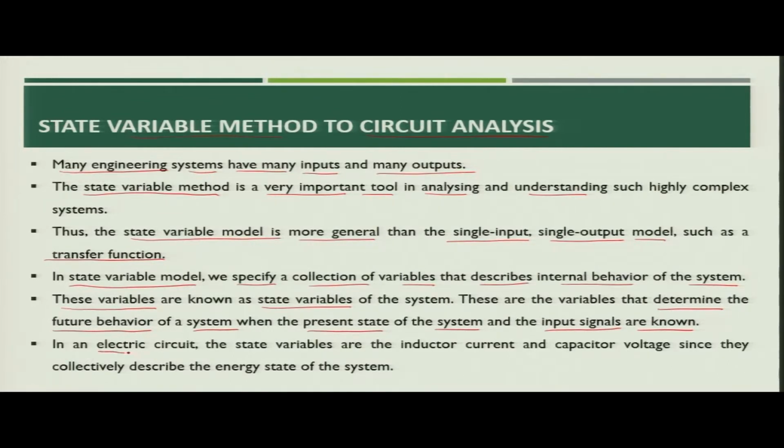With respect to our electrical circuit, the state variables we generally consider are the inductor current and capacitor voltages, because they collectively describe the energy state of the system. Now, let us see how we will implement it.